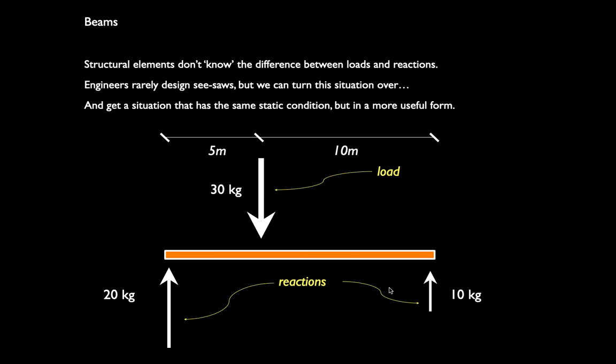So in a very short period of time, we've gone from thinking about what a vector is to taking an actual structural element and figuring out how it can stay not only in one place, but how it can also stay in the same orientation, right? How we can prevent it from translating and from rotating.